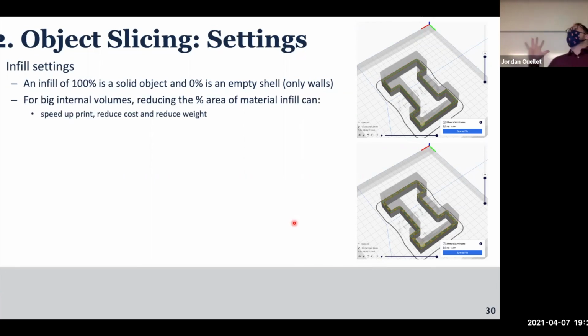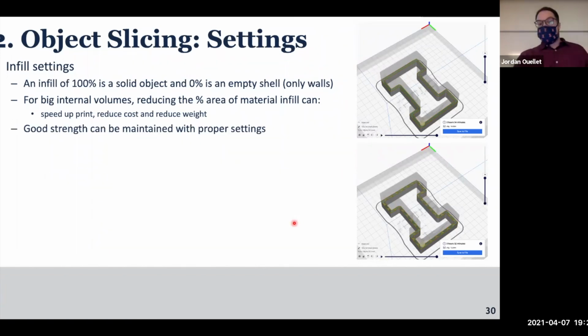If you have big structures like that, for example, you want to have a lower percentage of infill, obviously to reduce cost and weight, all while maintaining good strength. That's the priority in there. There are different patterns, like I showed during the break.